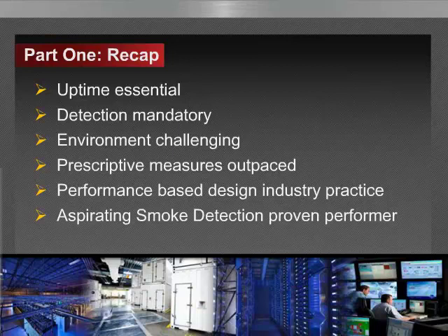All right. So technology innovations and business needs have outpaced prescriptive measures, leaving to question placement, spacing, and selection of suitable smoke detection technologies. The result is a shift towards performance-based design, which assesses applications according to specific environmental and operational conditions to meet particular facility requirements and owner objectives. The performance-based design approach is widely used and is employed to justify designs not covered by codes or where an improved level of fire protection is required.